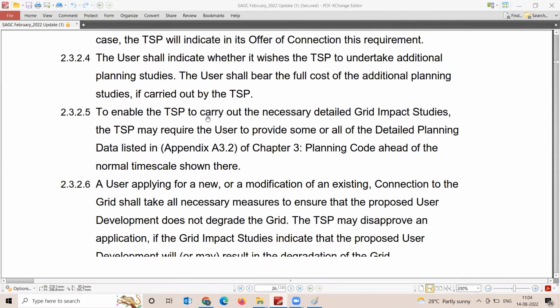If you take the Japan grid code, you cannot increase or decrease the energy produced by more than 1% every minute, which means if you're generating on average 100 megawatt this minute, next minute you can go to maybe 99 megawatt or 101, you cannot go beyond it, which is technically not possible in wind and solar. And then obviously they need to go with battery energy storage systems or some other energy storage system when they come to large scale solar plants, right? Why? Their grid is weak and that is mandatory for them.